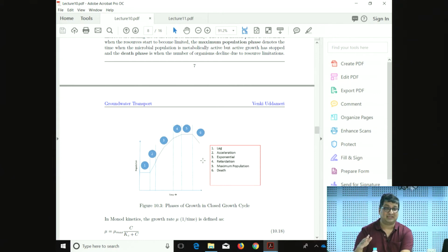So then what we see is elevated levels of protozoa, because protozoans actually graze on dead bacteria. When you start seeing protozoa populations increase, it's an indicator that our microbes are dying. So now we need to figure out why the microbes are dying. They could be dying because, one, our concentrations are very low, which is a good thing, so when you start seeing elevated levels of protozoa, you can say that, hey, I've actually cleaned up the site.